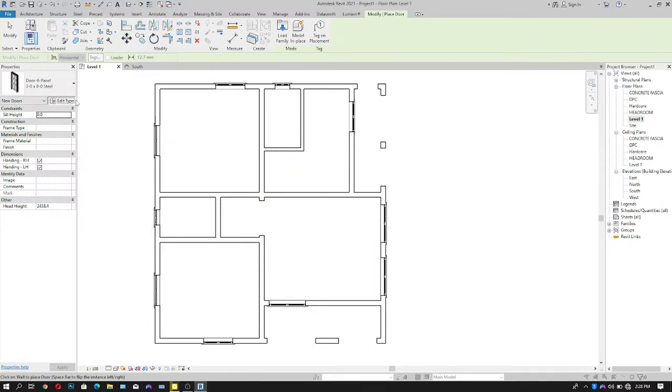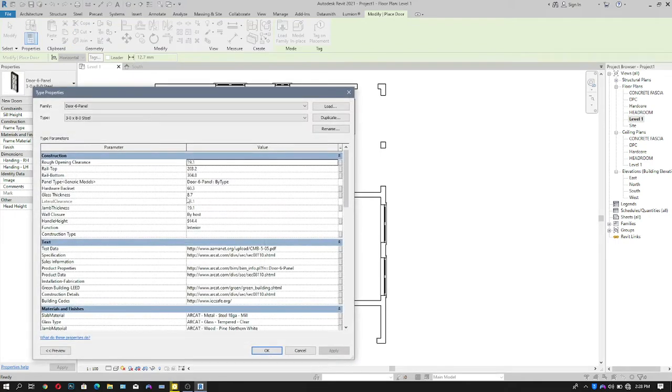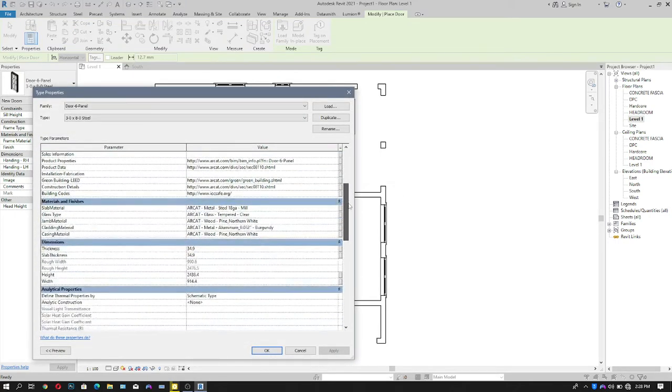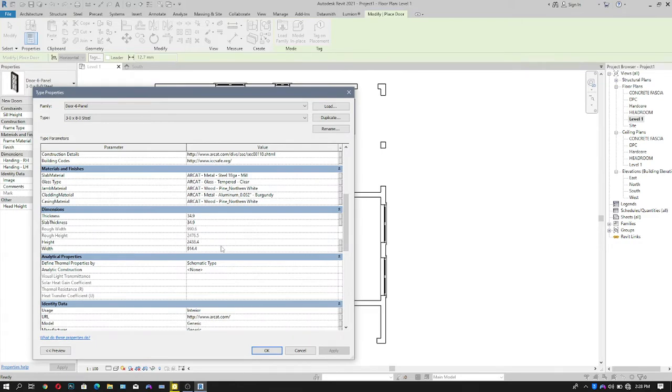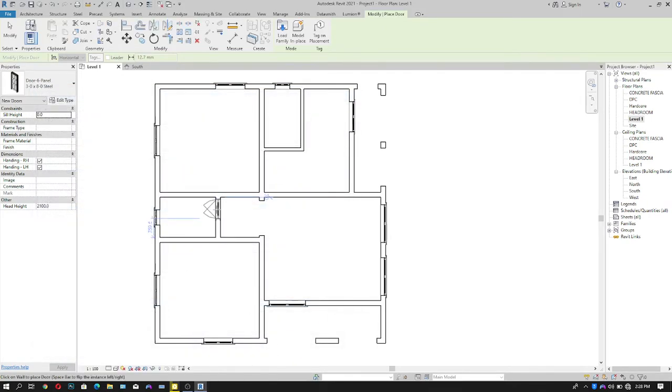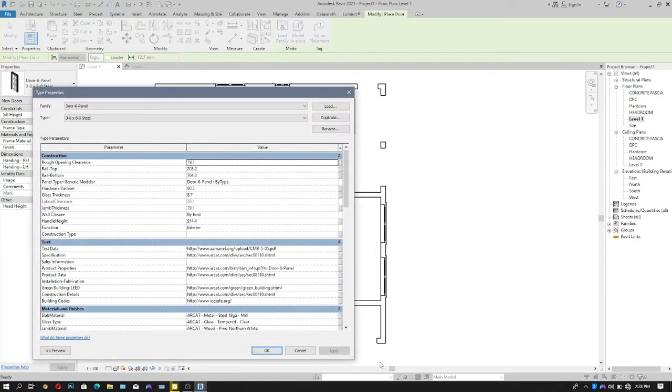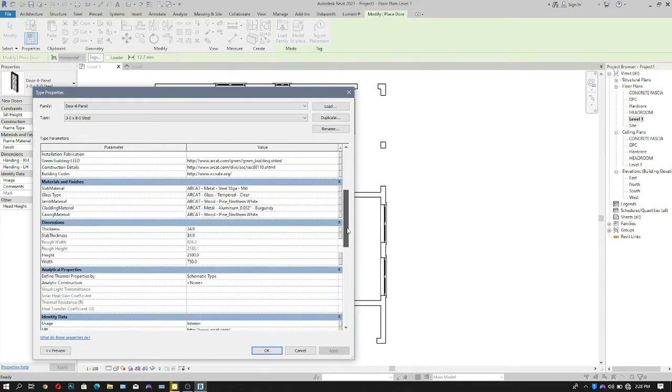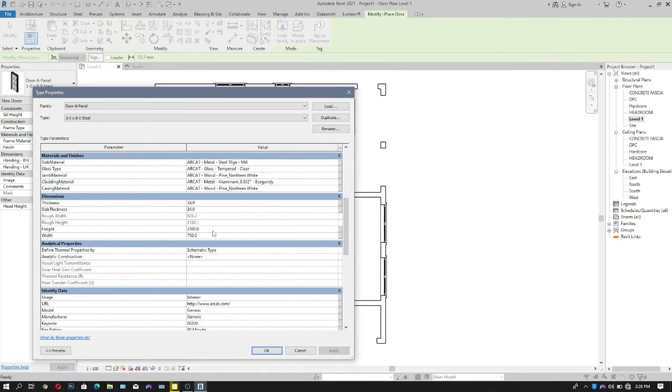So now before we place our door, we need to start placing for our toilets and store. So let's edit it to the desired specification. Look for height. As you can see, this is the height, it's 2.4. Let's change it to 2.1, and the width to 750, and click enter. Okay, place it and then place it. Now let's go back to edit it again. Look for your height, 2.1 is there. Change your width to 900, that's for our bedroom and kitchen.